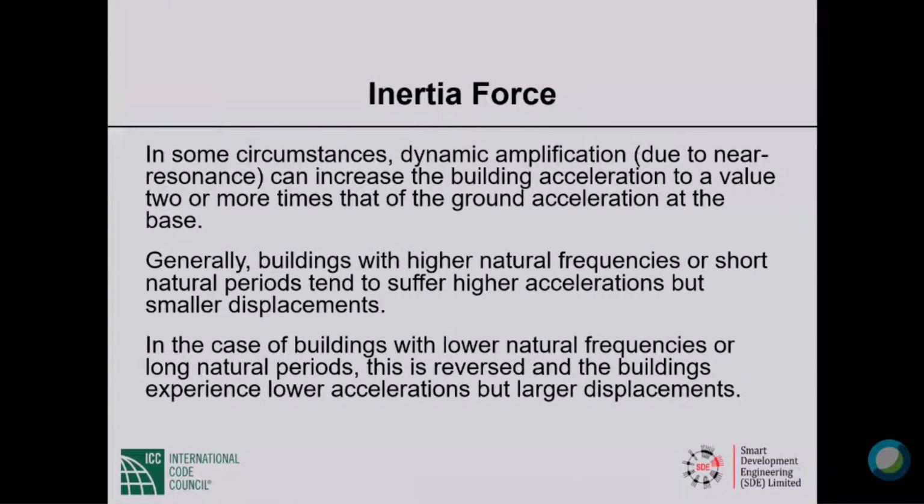Generally, buildings with short natural periods, those would be short, stocky buildings, tend to suffer higher accelerations but smaller displacements. And if it is taller, more flexible buildings, it is the other way. They suffer more displacements but less acceleration.